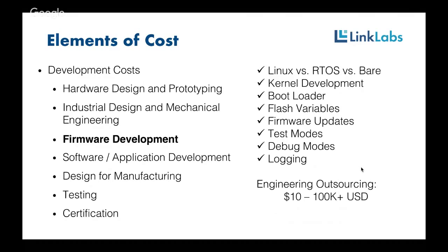There's all sorts of different things when you're doing even an RTOS or bare metal development, like building the bootloader, which is the thing that allows the system to load firmware either after it's been updated or when it's being programmed in the factory. Flash variables, think of it like the hard drive for a system. So if the power gets cycled or the thing gets unplugged or runs out of batteries, when it wakes up, it knows what day it is and how to behave.